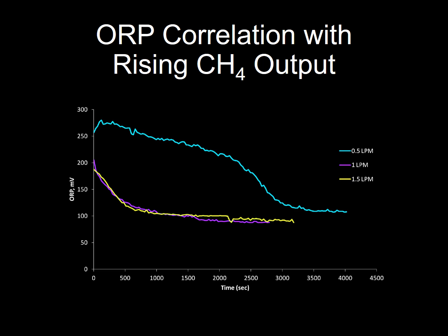So one thing to be considered here perhaps is that maybe it's more of a warning indicator as a surrogate monitoring tool, ORP for methane, versus an explicit quantification of what might be going on, kind of more of a signal to then go out and grab samples and take them to have a more accurate and robust laboratory analysis made.